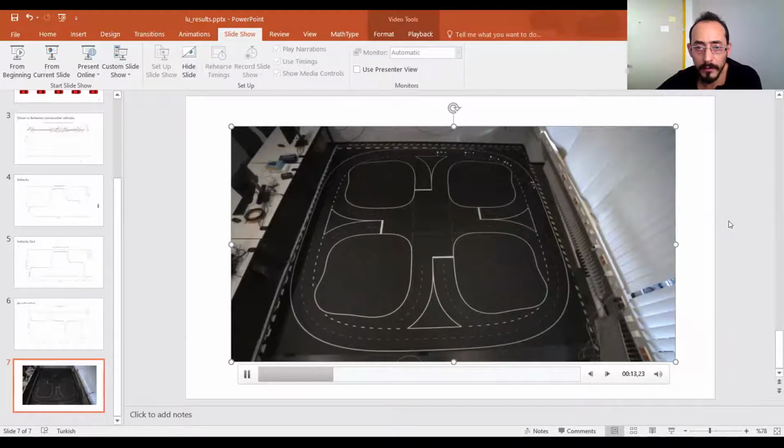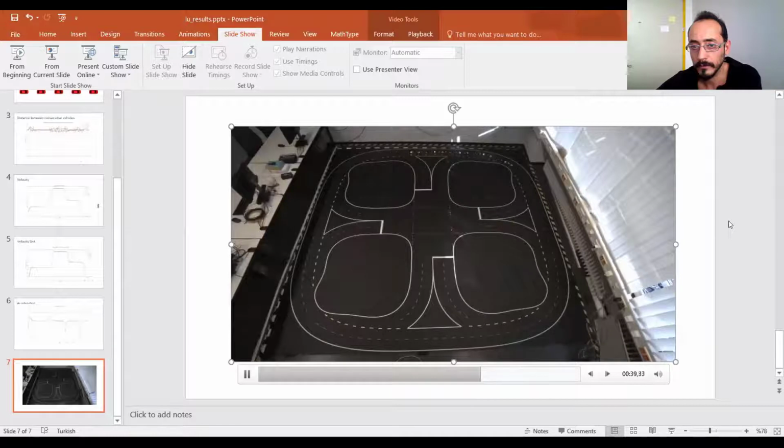As you see, it waits for other cars because we accidentally did not provide a non-zero penalizer value for its velocity profile tracking in the MPC formulation. So it couldn't follow the velocity profile from the beginning. Nevertheless, the code ran anyway.